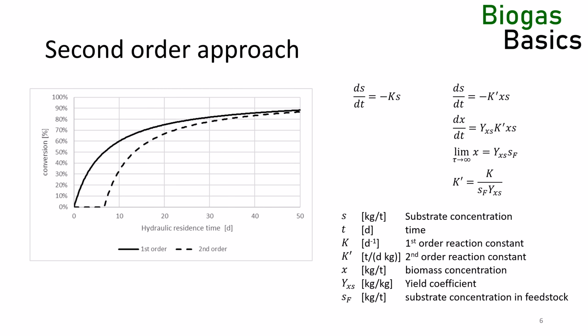The biomass concentration in a batch and continuous reactor are different. The batch reactor is diluted with inoculum. The inoculum is selected to have a minimal intrinsic biogas production itself. It has been taken from another reactor and has been transferred to the lab. Sometimes it is screened, and often it is starved to reduce its biogas production. In a continuous reactor, as in the CSTR with the feed stop method, the inoculum is at the steady state concentration, and it has not been transferred to a new environment. In a batch experiment, the biomass concentration is lower, and thus the observed pseudo-first order kinetic constant is lower. In a CSTR, the biomass concentration is higher and the observed pseudo-first order kinetic constant is higher.